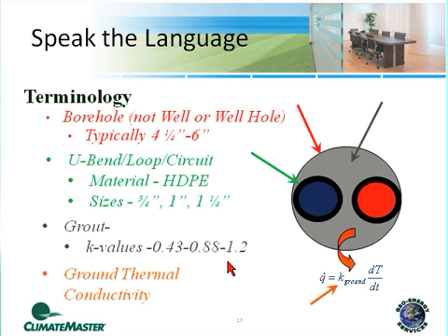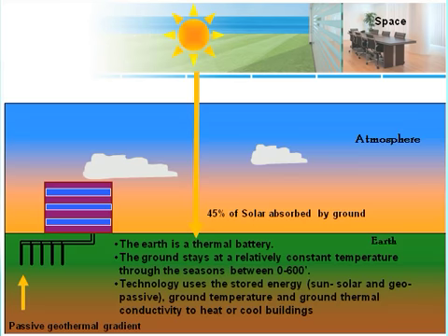I have a lot of contractors out there that tell me that if it's thermally enhanced beyond 0.88 or 0.95, they won't even bid on the project because they don't have the equipment and the capacity to handle the higher thermal conductivity grout. So you want to be careful about whether you're going to use what I call ultra thermal conductivity grout of a 1.2 value, or whether you can live with the 0.88 to 0.95 ranges. Very critical. But the goal here is to move energy between that fluid and that pipe and get it to the ground itself. And the next dominant characteristic is the ground thermal conductivity value. That's an important characteristic that we're going to get to in a minute, of how we obtain it.